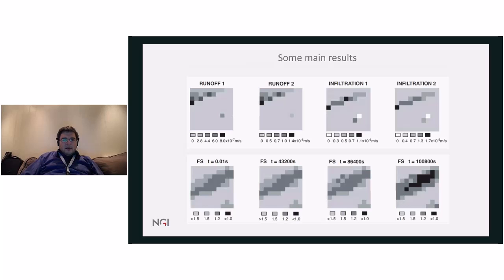Then, after one runs the model, the most important output is the distribution of factor of safety. Here we can see that the lowest factors of safety are obtained in these parts of the slope. So if we were to continue the evaluation here, these would be the areas where we should continue running a runout model. So this would be the initiation areas to be used in a runout assessment.